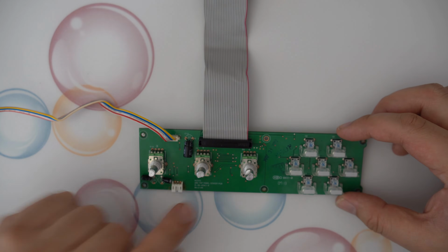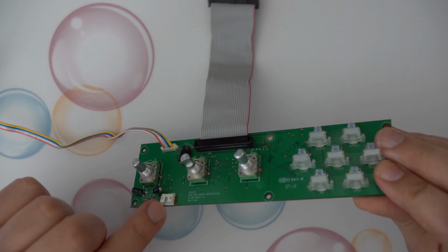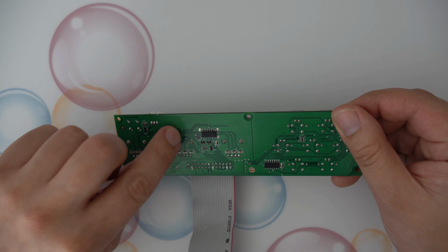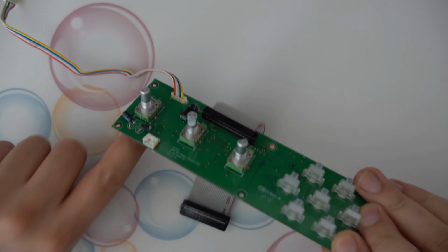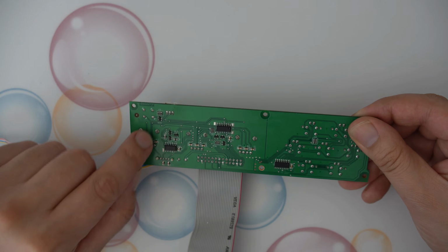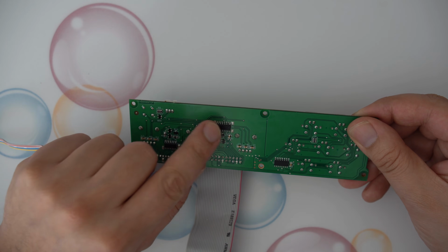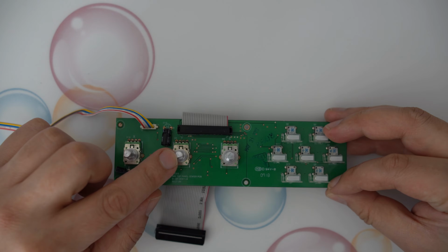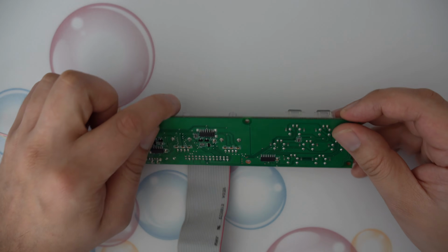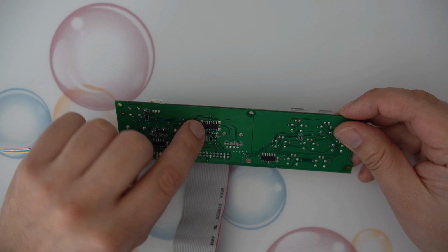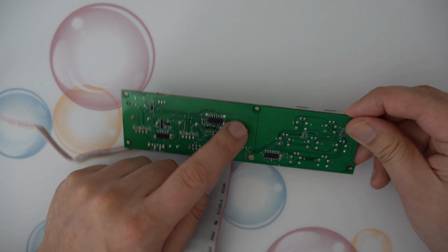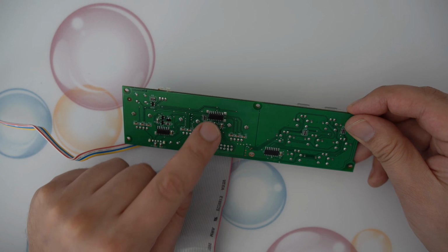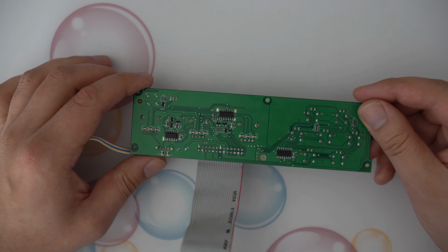So the only thing remaining as a possible cause of the failure are the potentiometers and the 3 chips. I think it's safe to say the potentiometers aren't the problem here, as it's highly unlikely they'll start sending random values all the time when they fail. Normally, when these fail, they stop picking up the movement. So I think one or more of the 3 ICs on the board are damaged. If we look at the traces, we can see they all lead to the middle IC here, so I'm placing my bets on this one.